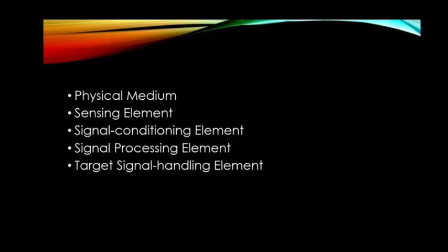The signal conditioning element serves the function of altering the nature of the signal generated by the sensing element. Since the method of converting the nature of the signal generated in the sensor to another suitable signal form, usually electrical, depends essentially on the sensor, individual signal conditioning modules are characteristic of a group of sensing elements.